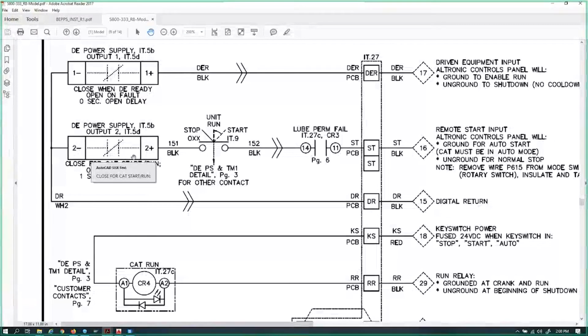If the light remains on and the switch is in the run position, but we want to test the contacts of the switch, we can jump right over here to this side and do the exact same thing real quick. We should still see 24 volt reading. Again, we don't have 24 volts here. We have a ground all of a sudden here. Make sense? So the last thing is our loop permissive fail relay.